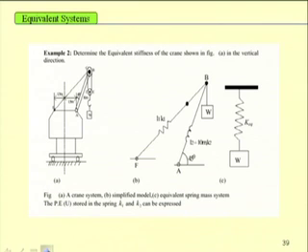So, to find equivalent stiffness, for example, let us take this crane system. In this crane system, there is this rod and this beam. One can find the equivalent spring for this one, and finally, as the mass is moving in the downward direction, one can find one equivalent stiffness of the system. So, this rod is subjected to axial force, then one can find the strain energy associated in this axial direction. So, one can find the strain energy here for these two elements and then equate it to that of the equivalent spring.